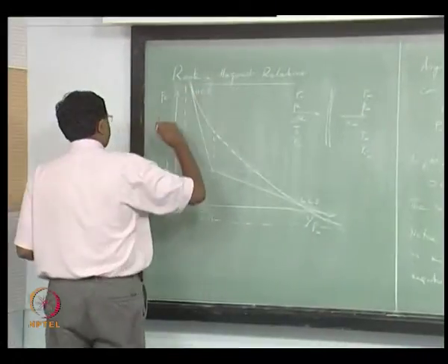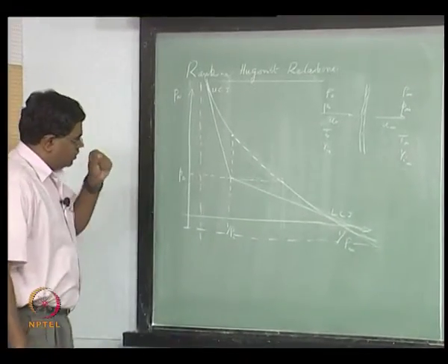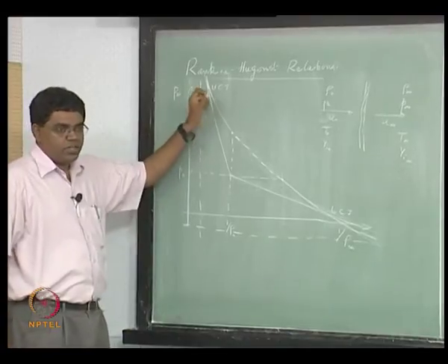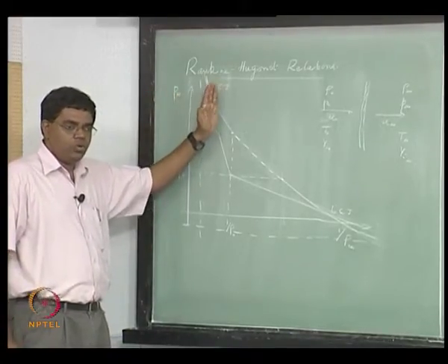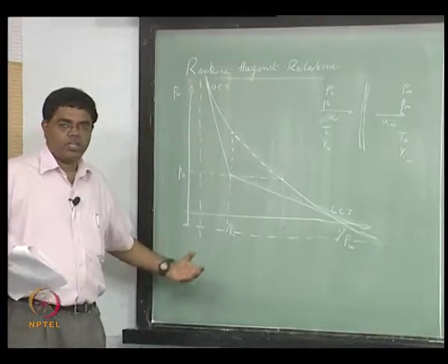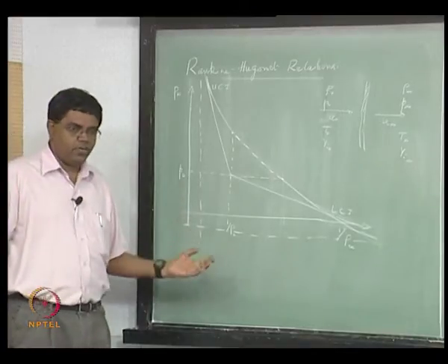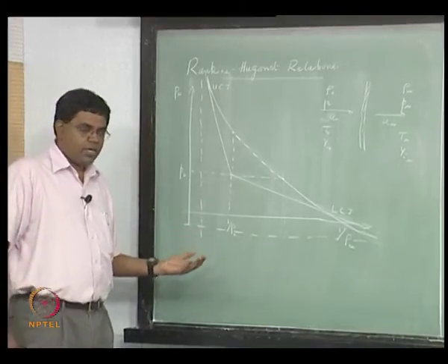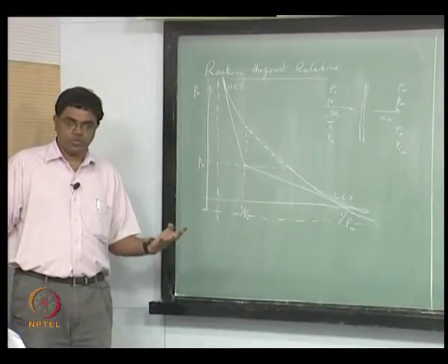Obviously, any point that is a solution of both, an intersection of the Rayleigh line and the Hugoniot, is found by solving them together, right. The Rayleigh line has its P infinity and 1 over rho infinity showing up, and the Hugoniot curve has its P infinity and 1 over rho infinity showing up.